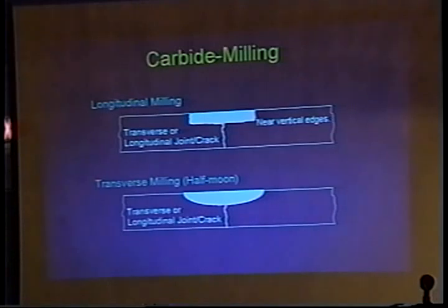Same thing here, only this is at a joint, and what they're doing is placing in joint filler to reestablish that joint. You can't let this patch go right up to the next slab adjacent to it, because once that slab starts moving, if it's trying to expand in hot weather or something like that, that patch will pop right out. So you want to reestablish that joint, just like the existing concrete has.